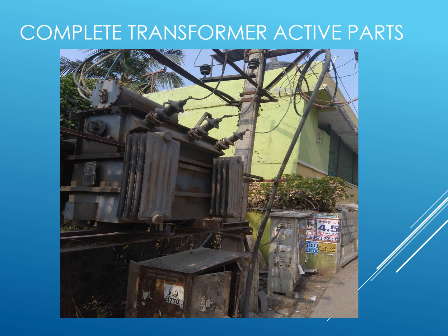I said this is a static device since it has no rotating parts. But in motors and generators, there are rotating parts, so losses will be high in motors and generators. But in transformers, due to the absence of rotating parts, losses will be very less. So efficiency will be very high.